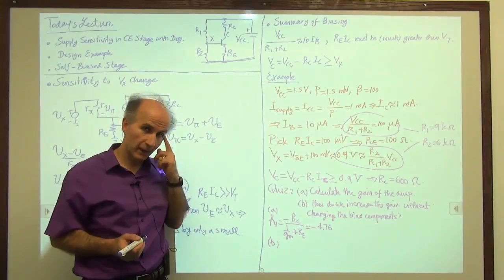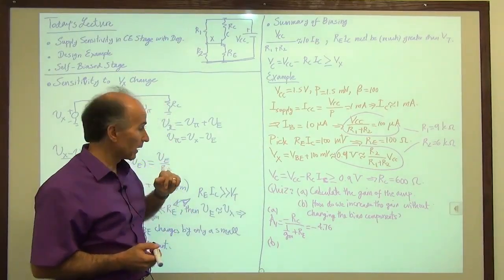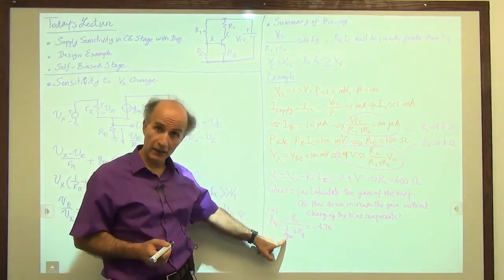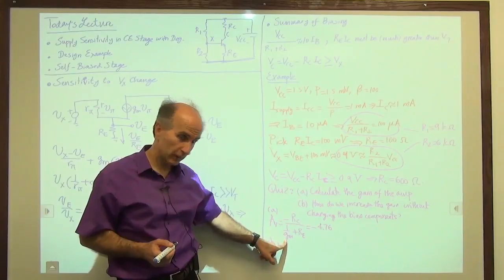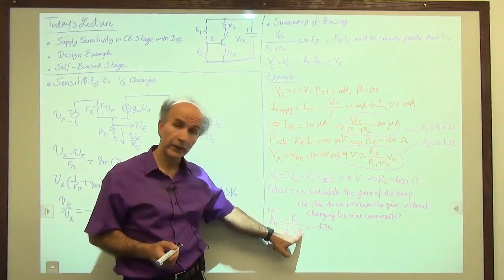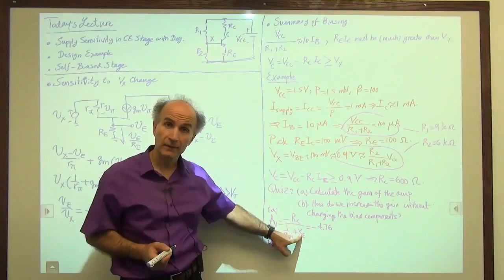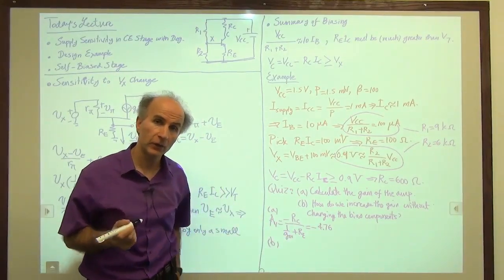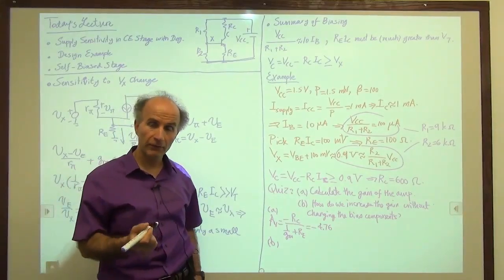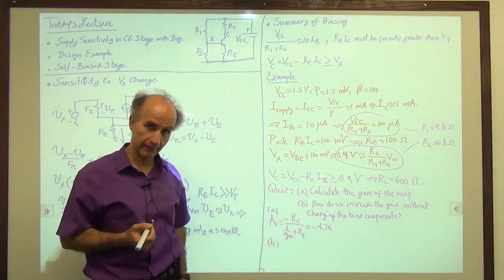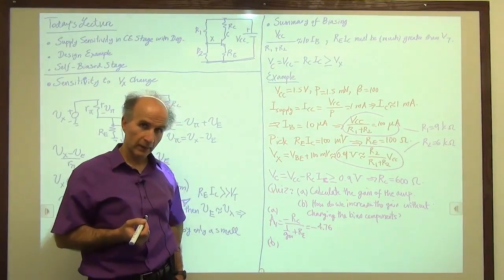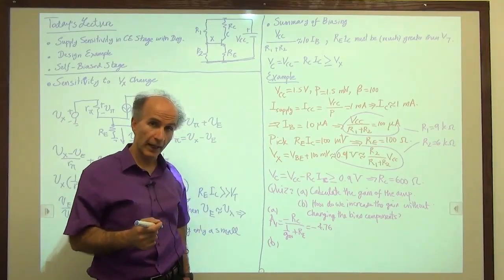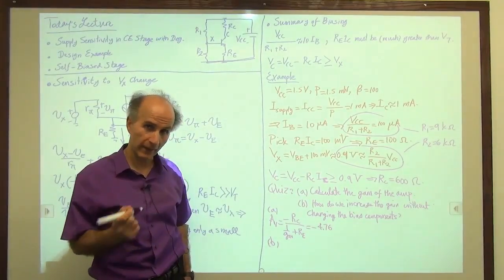So when we think of AC, we are thinking maybe, if I look at this equation, I can increase this gain by trying to decrease RE for signals, not for DC, but for signals. So how can I reduce RE for signal frequencies that come into the circuit? Well, we know a device whose impedance goes down as the frequency goes up, and that's a capacitor.